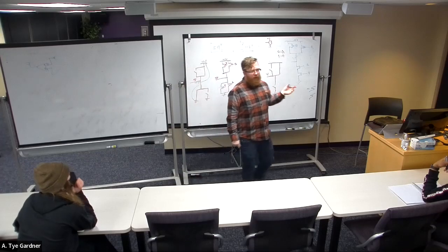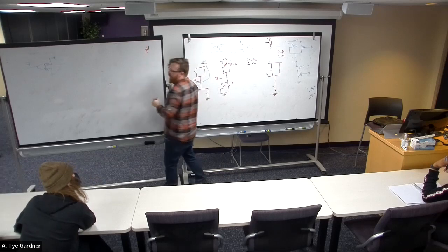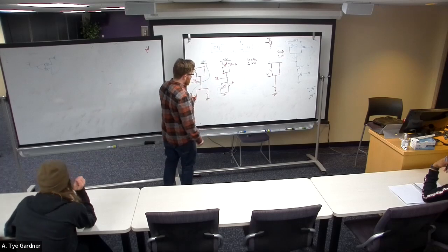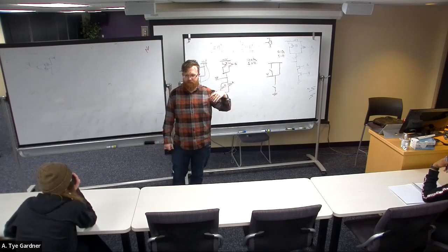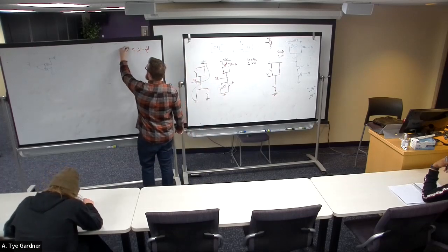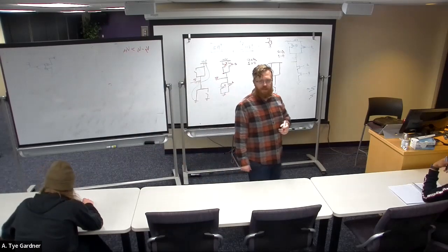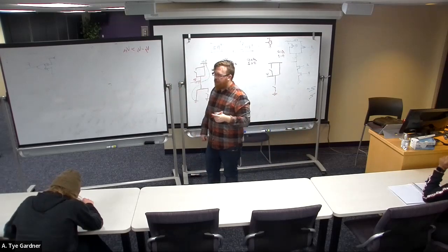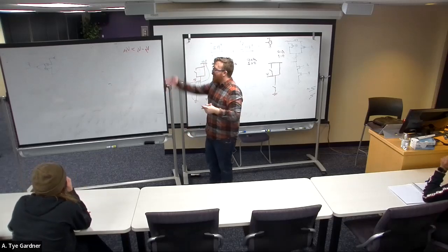So in order to be on, there's the gate voltage, VG, and then we have the source voltage, which is going to be the bottom one. That's the source. One of the nodes is the drain, the other is the source. So VG minus VS has to be greater than some threshold, some amount of voltage, okay? This is the condition for turning on-ish, under certain conditions. There's a bunch of qualifiers to it. Well, let's go with this equation.